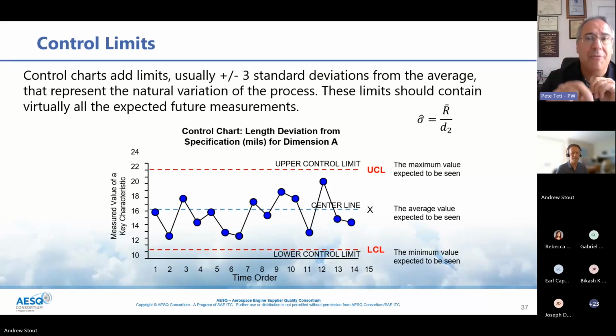And that's why we would want to investigate a point outside a control limit, anytime outside an upper or lower, because that's a rare event to happen due to chance. It's probably due to an assignable cause. And that's what we're showing here with a control chart. Plus or minus 3 standard deviations was set by Walter Shewhart. He felt that was the right number of sigmas away that would mitigate us chasing special causes that aren't there and missing special causes that are there. Again, making a type 1, type 2 error using a control chart.